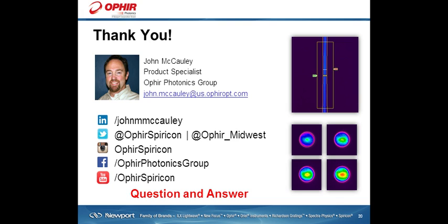There are a lot of different factors that play into how often you take measurements. Me, personally, I've never owned a laser system, but if it were me, I would, number one, take measurements at your system runoff. You are paying a lot of money for this laser system. You should look into investing in laser measurement products early in the life cycle of that particular laser system. Take measurements at system runoff. Take measurements after the delivery of the system to make sure nothing has changed.